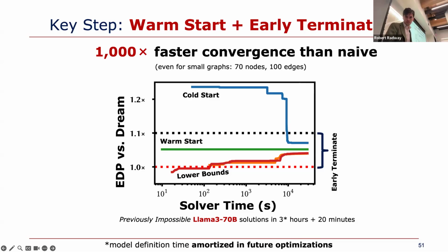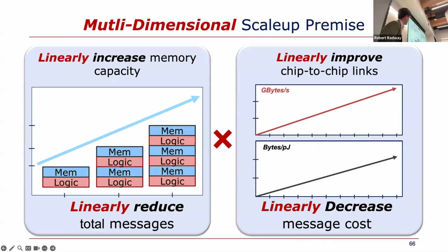But one thing I'd like to point out is this idea of scalability, right? We said our memory is scalable because it's dense and you can lithographically scale it. But the other way that you could potentially scale it is by having many layers of devices. I'll talk on some of that at the end. If you can increase your capacity by increasing your devices per chip by doing 3D integration instead of 2D integration, that gives you an increase in your per chiplet capacity.